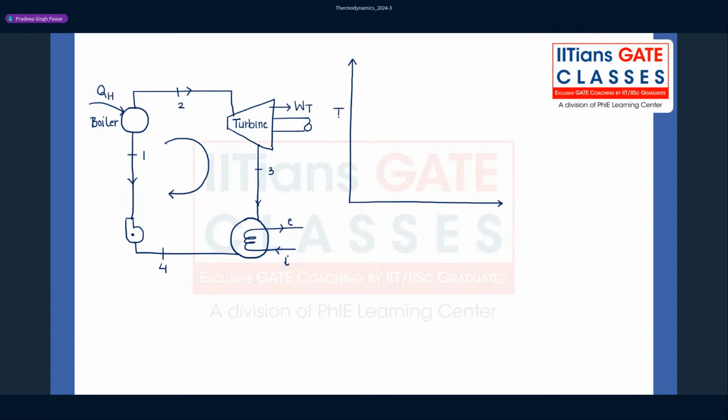We draw the TS diagram. Okay, so we are here. Let us say state 1. Now not state 1, the state 2. That is, steam is entering the turbine. Then the steam expands. Okay, we come to state 3. Then there is heat rejection in the condenser. We reach state 4, which is saturated liquid state.